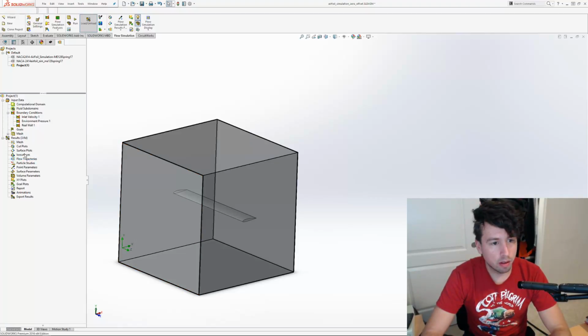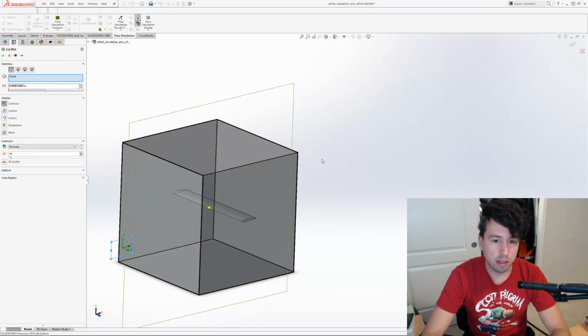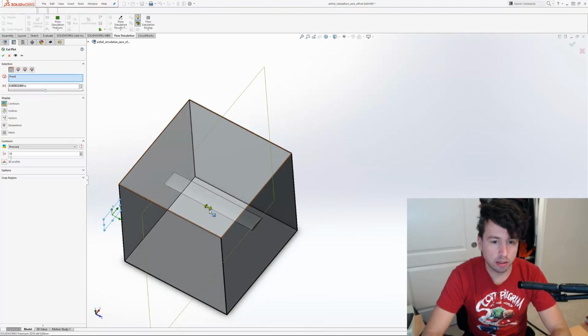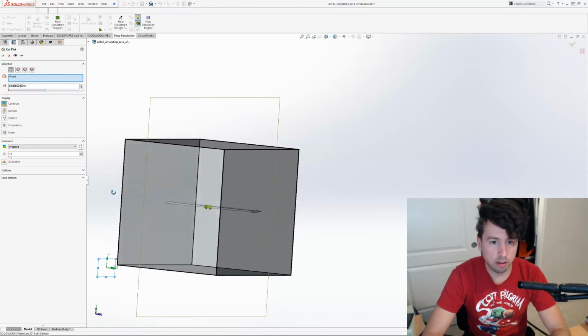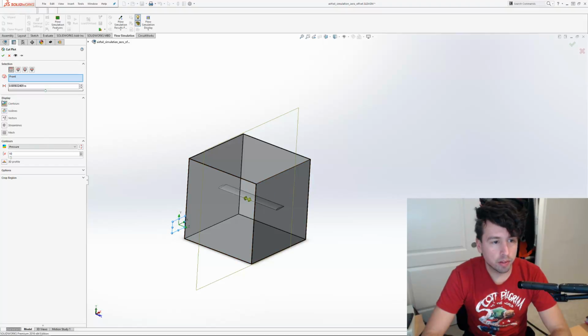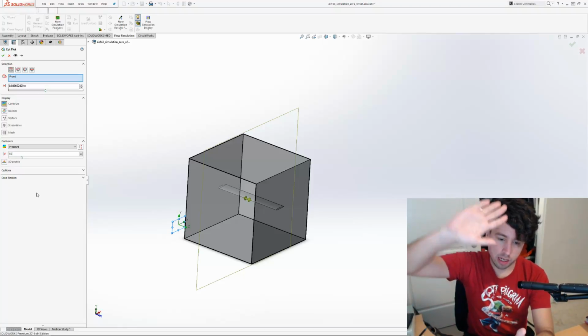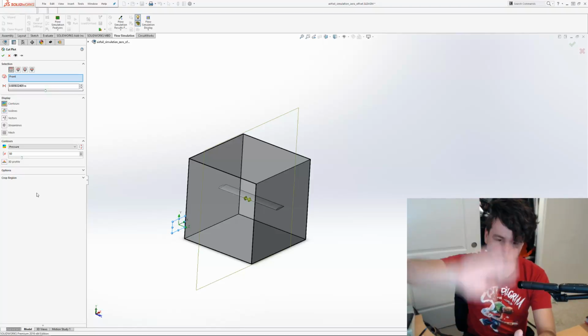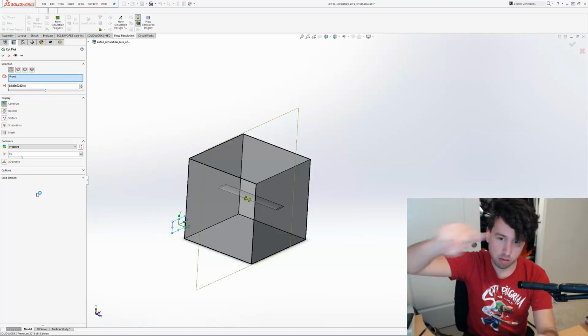So we'll do a cut plot. Generally it does a mid-plane cut plot with a certain thickness to get the calculation. So let's display contours. We'll do it for pressure, and let's just do 50. We can do a 3D profile. I'm not going to really go into that right now. I just really want to see if we're looking at what this is giving us. It's a plane with pressure contours around that airfoil.